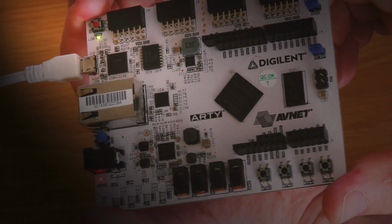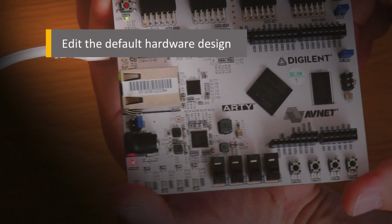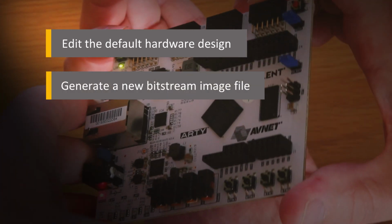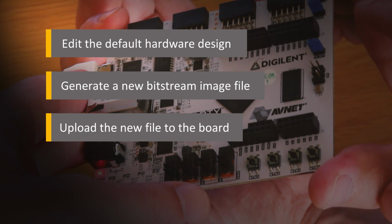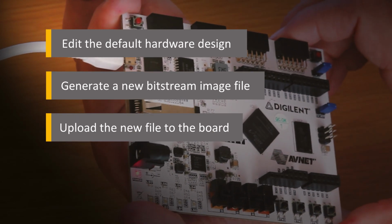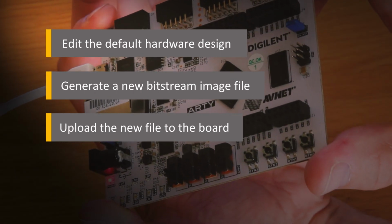So just to recap what we've done here, first we made some changes to the physical design in the Vivado project block design editor, then we validated the code, generated a new bitstream image file, and then we uploaded this to the board and checked the result. And now that you've done this, you can follow these steps every time you want to make changes to the hardware design and want to verify them on the board.